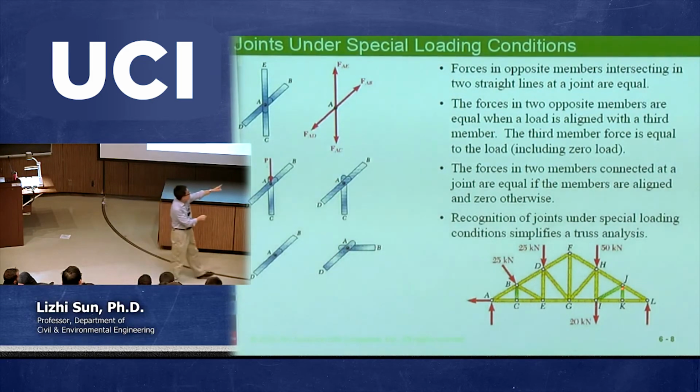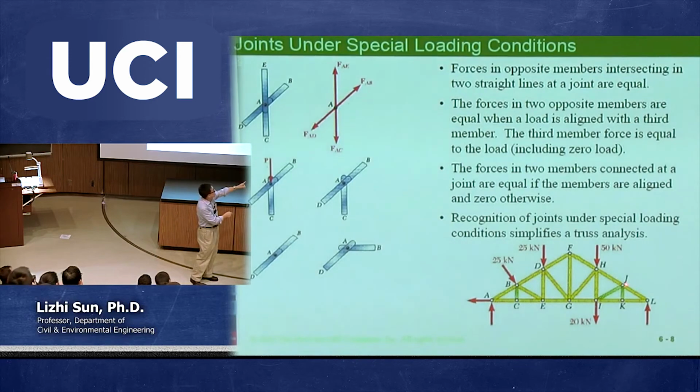So now, by looking at joint J, obviously you can say there are 4 members. I agree. But then I'm going to create the free body diagram of joint J this time. I cut this one, I give 1 force. I cut this one, I give 1 force. I cut this one, I give 1 force. I can also cut JK, but JK's force equals 0.